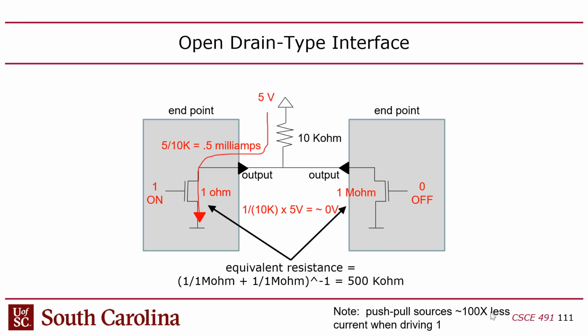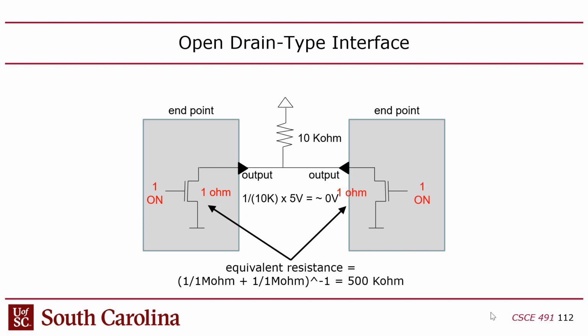And then if you turn on both, if these guys both turn on their transistors, they're both pulling down, meaning they're both trying to talk at the same time, so there's a conflict. That's not catastrophic because now you just have about an equivalent of 2 resistors in parallel down to ground, and then a voltage divider with this 10 kilo ohm up.